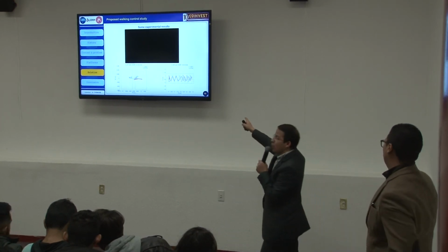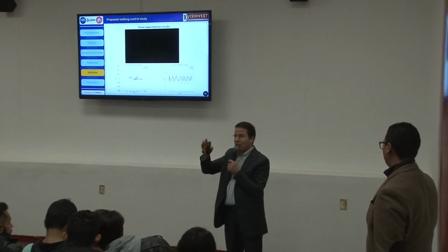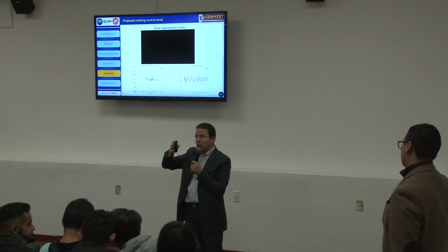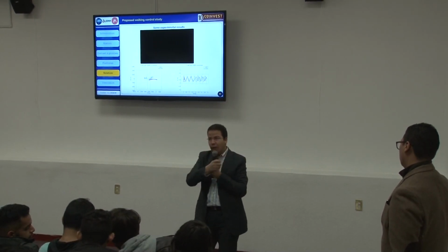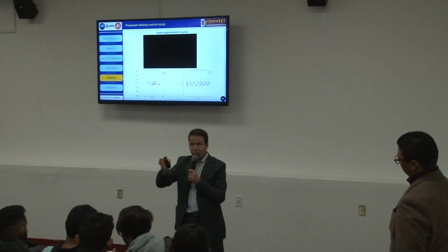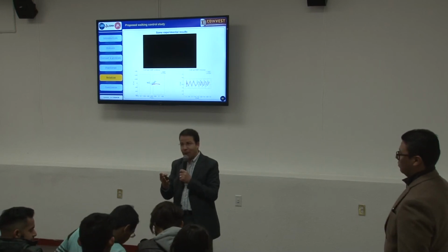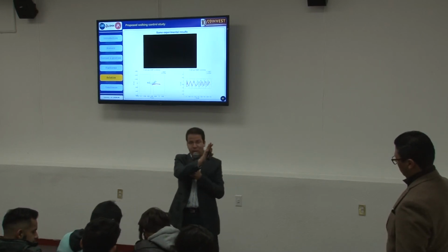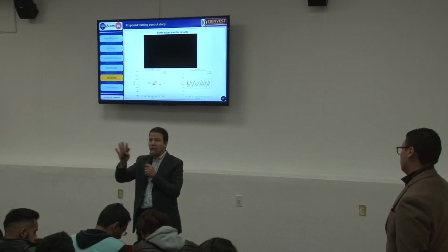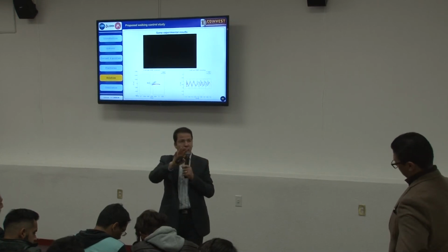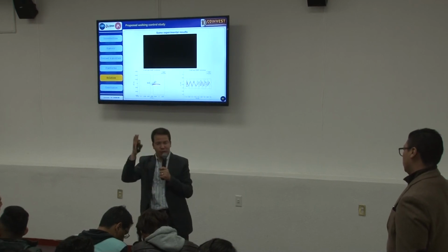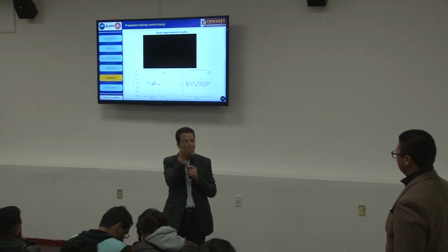Okay, the solution that we have proposed here is very specific. I can re-explain the basics. I said that in the literature you can find many solutions. They consider each phase alone, and they design a control for the single support phase, for the double support phase, and they have to support the external disturbance coming from the impact. In our case, for sure, the model is discontinuous, but for the controller, we have no distinction between the single support and the double support. The controller is continuous all the time, and it's the same controller working for single support, double support, for all the phases. This is the particularity.